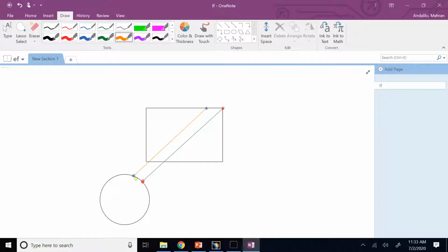If you use the tangency method, tangency means what is the direction of the tangent line to the profile at that point? The problem is when you have a profile that has sharp corners, or basically it's not a smooth profile, at those non-smooth corners you don't have a tangent line.